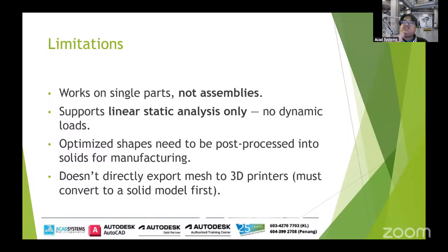Let's say you have an assembly of a suspension system, for example, in a car, and you want to optimize a bracket that's holding your roll bar or maybe your wishbones. When you have those types of scenarios, make sure you select just the brackets and do the shape generator on it.